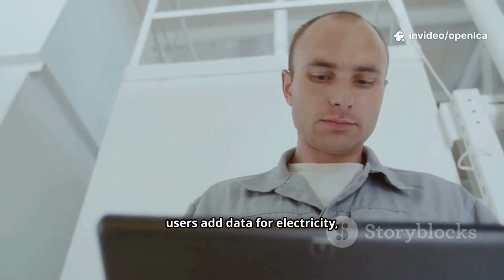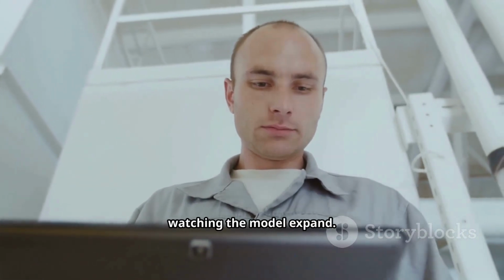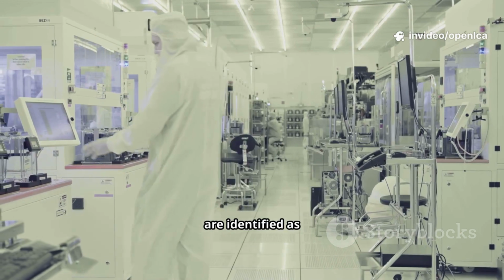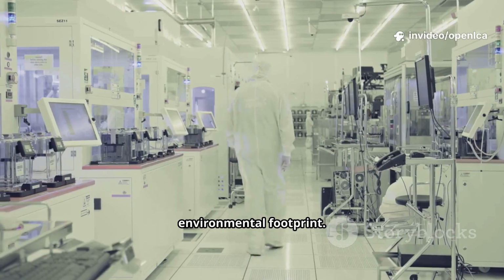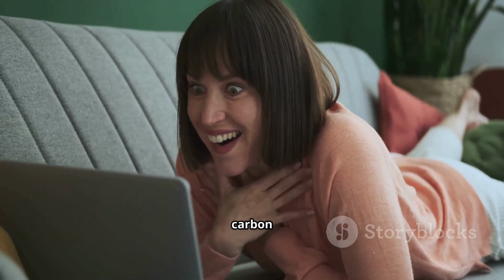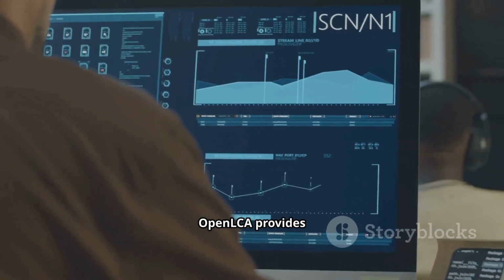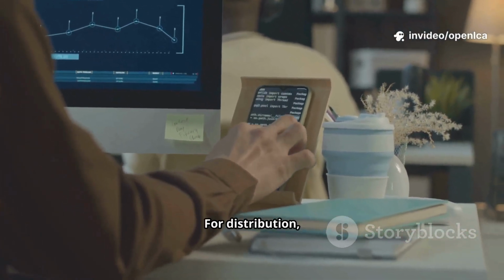For manufacturing, users add data for electricity, heat, and chemicals, watching the model expand. Chip fabrication, battery production, and screen assembly are identified as major contributors to the phone's environmental footprint. Results show that manufacturing is responsible for the largest share of carbon emissions, often more than half of the total. openLCA provides energy demand charts and a breakdown of emissions for each stage.